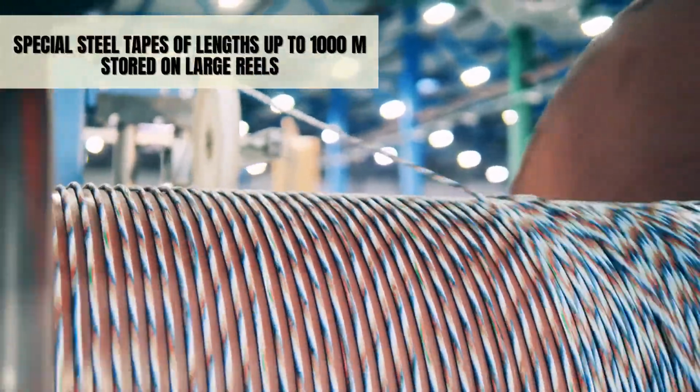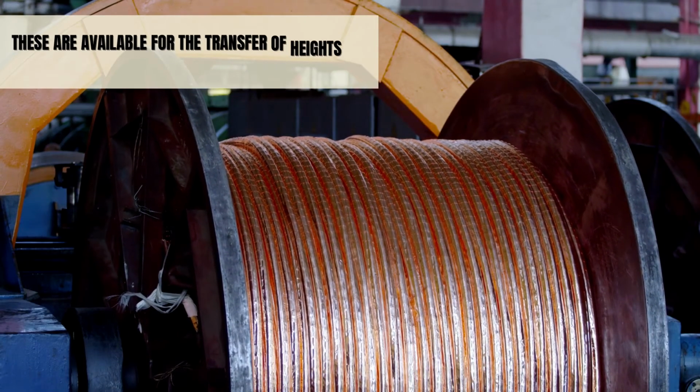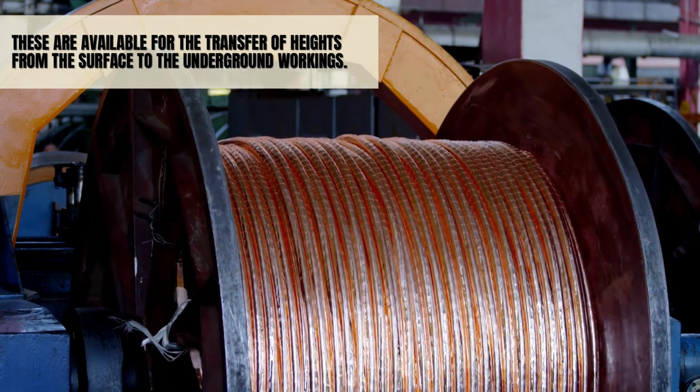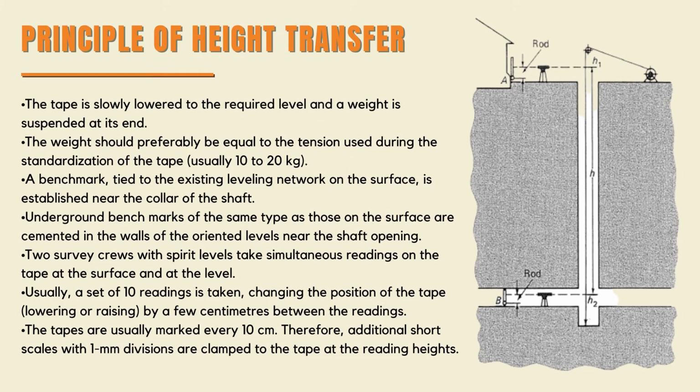Special tapes of lengths up to 1,000 meters stored on large reels are available for the transfer of heights from the surface to the underground workings. Principle of height transfer. The tape is slowly lowered to the required level and the weight is suspended at its end. The weight should preferably be equal to the tension used during the standardization of the tape, usually 10 to 20 kilograms. A benchmark tied to the existing leveling network on the surface is established near the collar of the shaft.